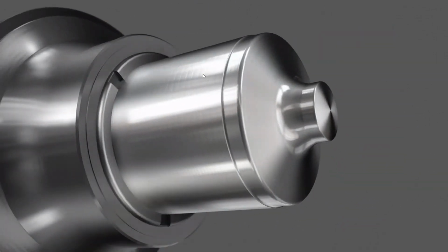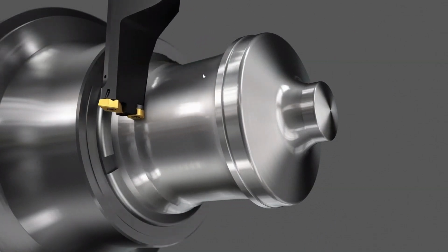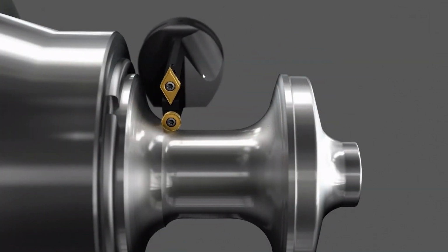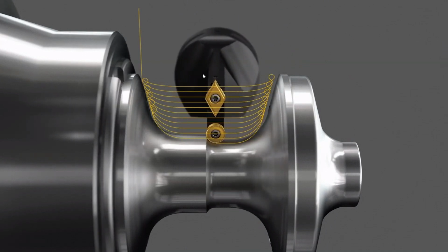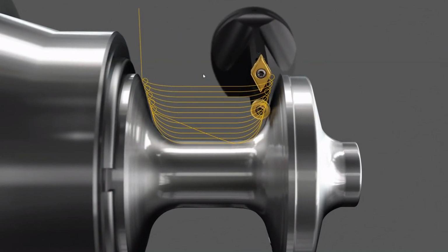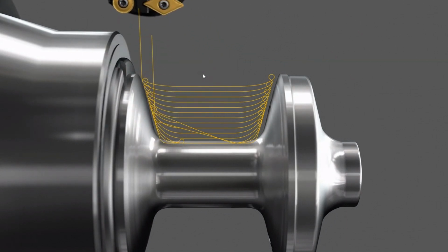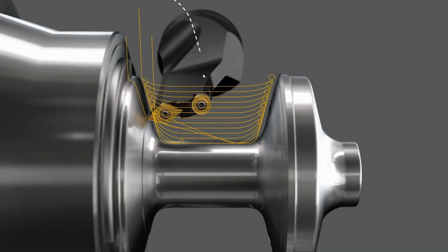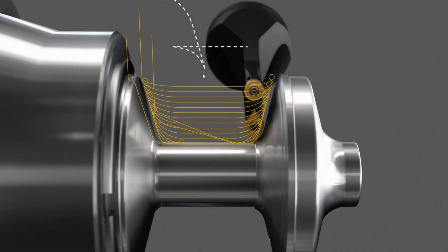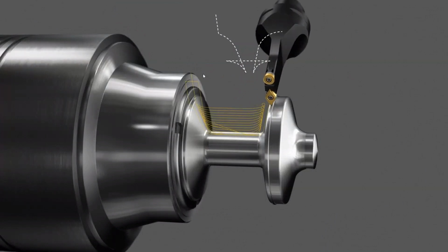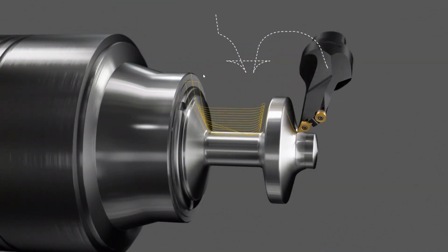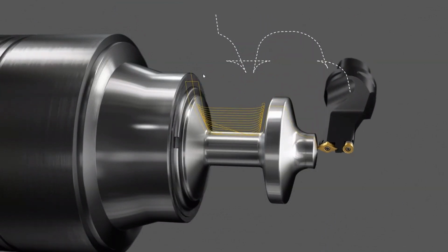So you can get an idea of what the tool path looks like. You notice that these holders actually have two inserts on them, so you can flip it 180 degrees and utilize both sides of the turn tool. So one can rough and do a trochoidal adaptive turning, and then you can flip it and do a simultaneous B-axis, actually A-axis turning operation. So really, really slick solution. Definitely the future. So look out for that. That's going to be something you'll see more and more in CAM software as well as multitask machines.